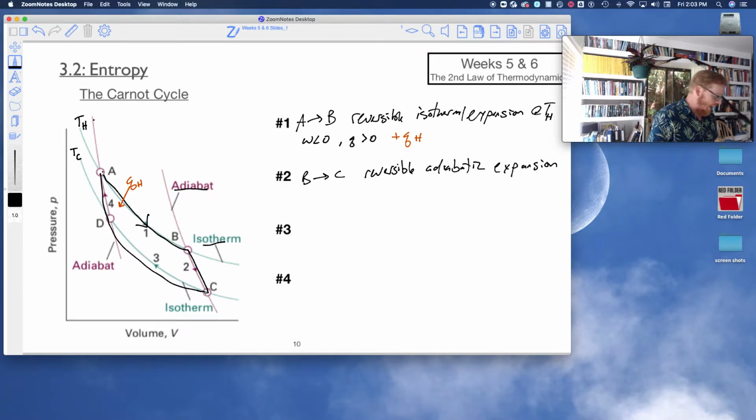Okay, and we will note a few things here: the total change in entropy is 0 because it's reversible, so that is also applying to situation number 1. But we also note that there's a temperature change. So the temperature has to go from T hot to T cold, as we noted on these different isotherms.